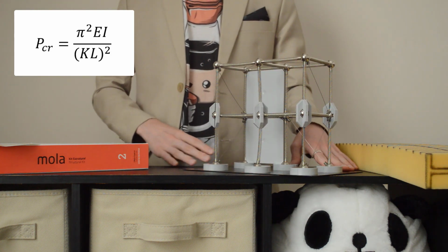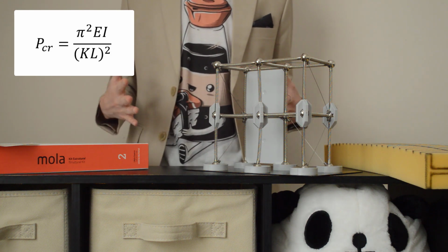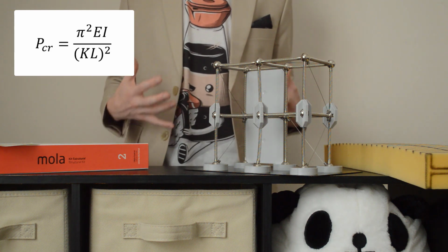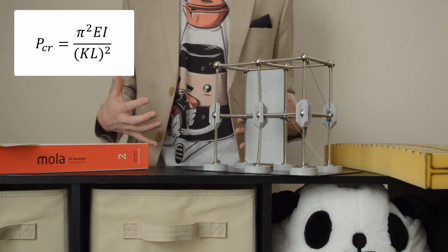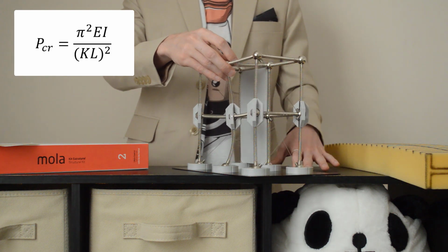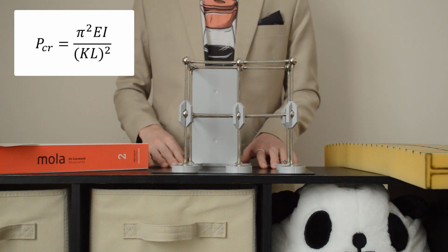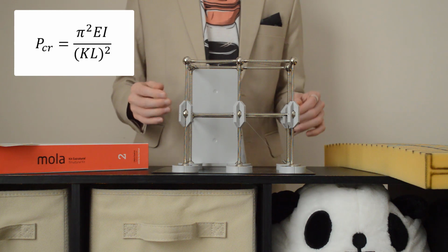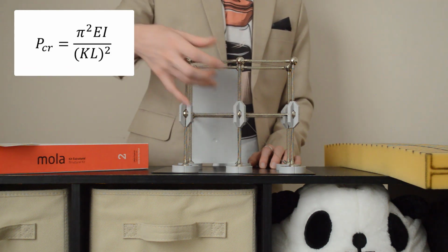So this all leads us to the final question. If we can have different values for the same variable about 2 different axes, is it possible to create a scenario where we don't know for certain which axis will fail first? Well, let's look at this column again. It buckles in this direction, right? It buckles into the long side of the building. Now, it's doing that, of course, because its unsupported length is double what its unsupported length is in this direction.